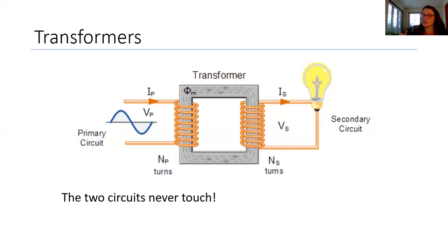Through power lines, you keep a really high voltage. The higher the voltage flowing through your power lines, the less of a power drop you have as current enters the house. It's to maximize energy transfer. So you transfer energy at high voltage and then you step it down as it comes into residential areas and into houses. So transformers are used all the time all around us.